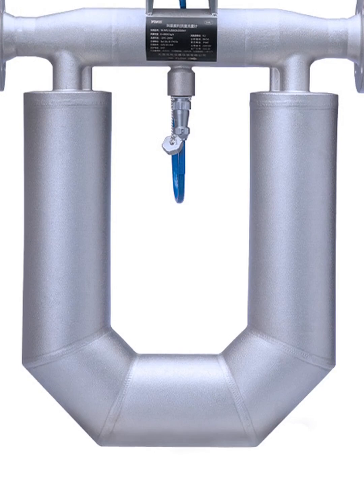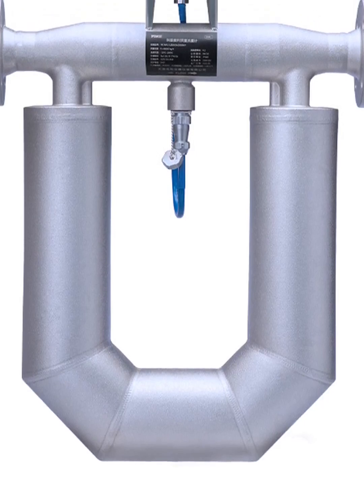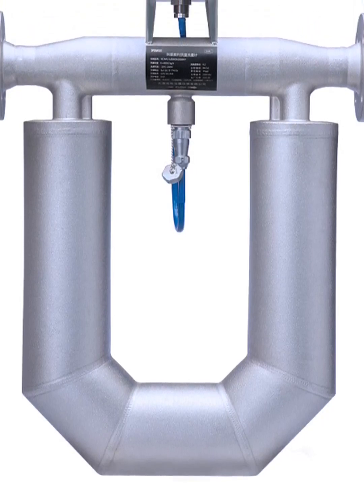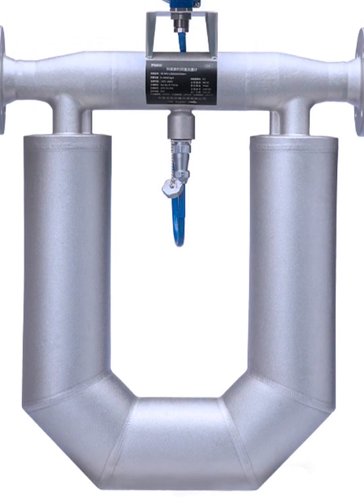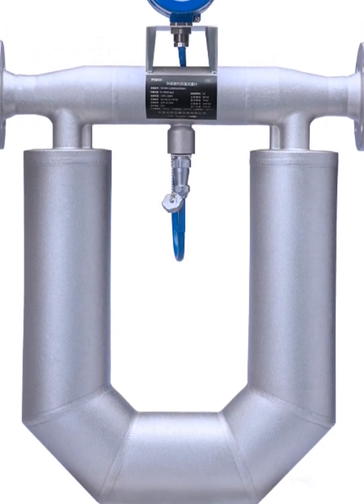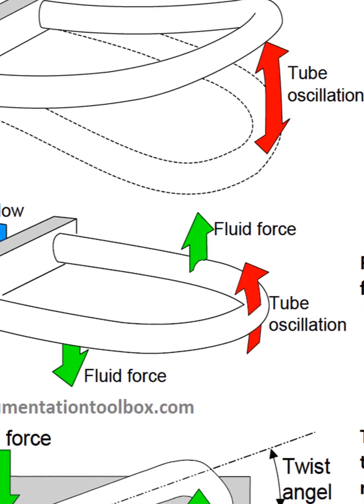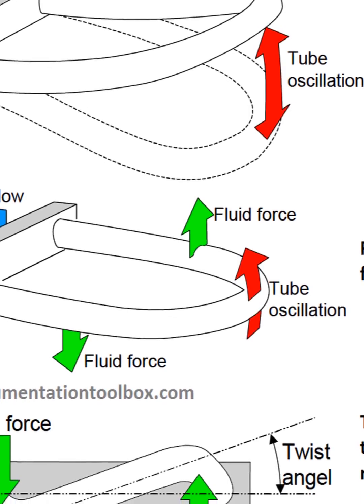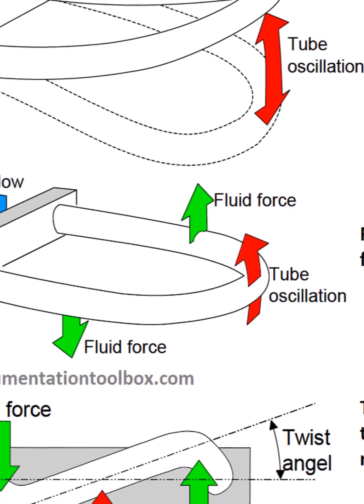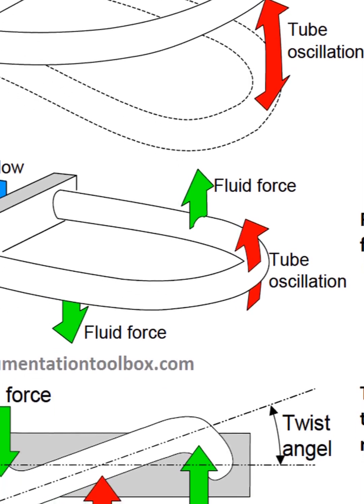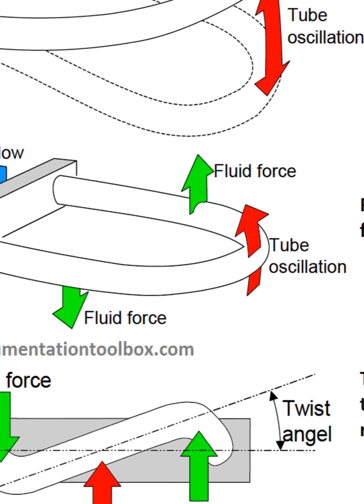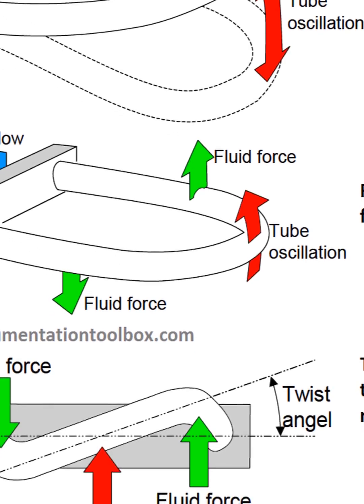rate. In a Coriolis meter, this principle is ingeniously scaled down and applied within an oscillating tube system. Instead of a continuously rotating planet, the meter's flow tube, or tubes, is electromagnetically actuated to vibrate, typically at its natural resonant frequency.